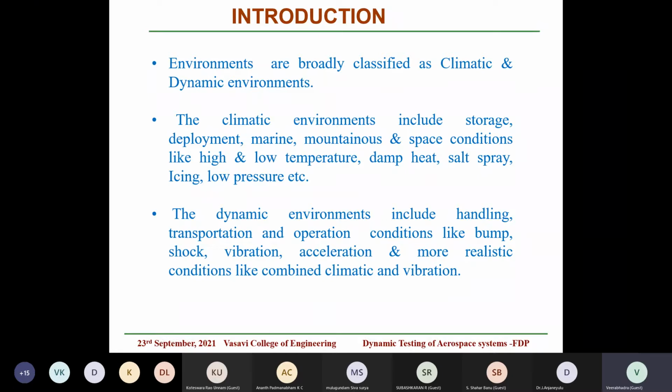Like when you are handling, if you suddenly drop, how to overcome the failure, or what happens when you are transporting some critical system by road, air, or rail. The system is going to be subjected to different environments, and some vibration levels will come, and how to mitigate the vibration levels or protect the system from these levels. Also, our road conditions have different troughs or road breakers, and these also introduce some shock, or what we call bump. These also need to be simulated and tested.